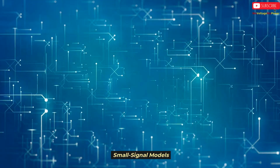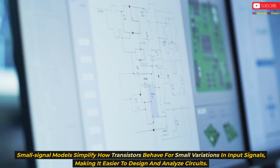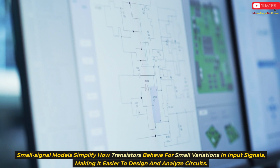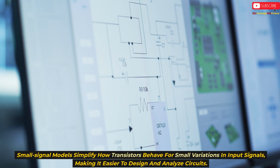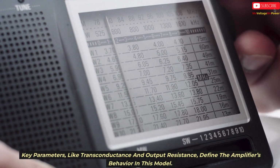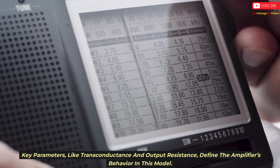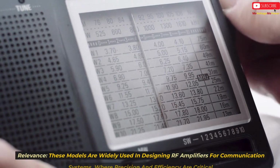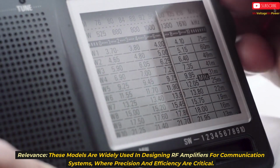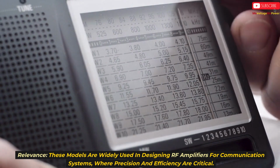Small signal models. Small signal models simplify how transistors behave for small variations in input signals, making it easier to design and analyze circuits. Key parameters, like transconductance and output resistance, define the amplifier's behavior in this model. Relevance. These models are widely used in designing RF amplifiers for communication systems, where precision and efficiency are critical.